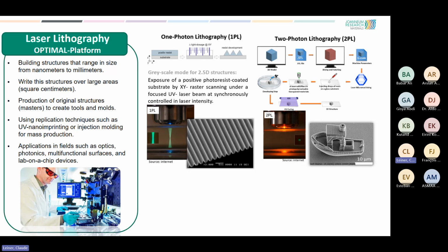You can make stamps out of them, and use nanoimprint lithography to reproduce them. So you're using what you're making here, then you're putting nickel or some metal onto it. Then you are removing the polymers. Then you have a metal stamp. And with the metal stamp, you can reproduce your structures in a nanoimprint lithography process. So these structures are reproducible with this process.